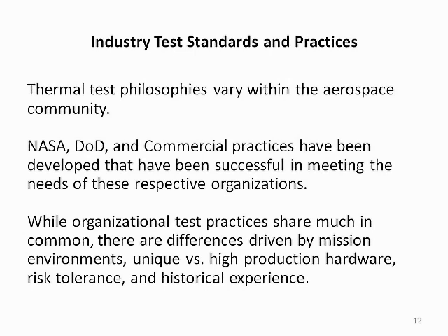While organizational test practices share much in common, there are differences driven by mission environments, unique versus high production hardware, customer risk tolerance, and historical experience. JPL, for instance, has a culture grounded in deep space missions involving long cruises with little temperature cycling, while Goddard Space Flight Center and DoD missions are primarily Earth orbiting.